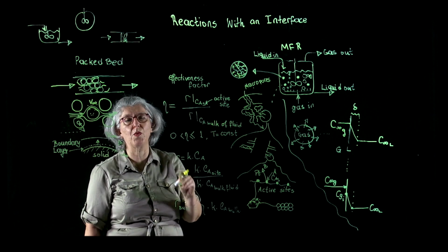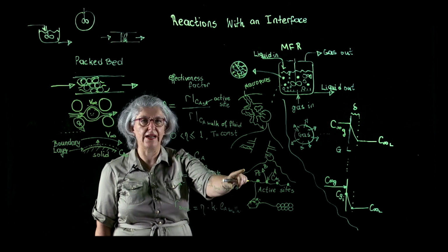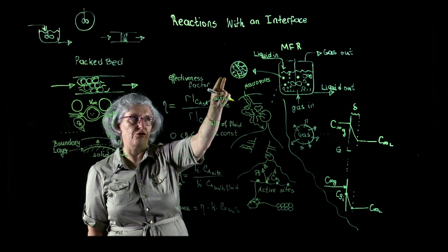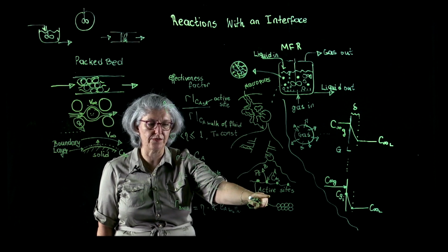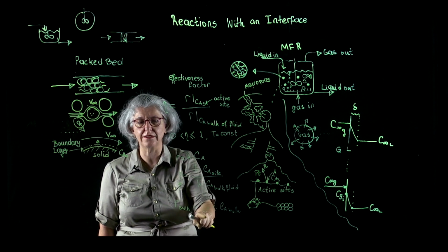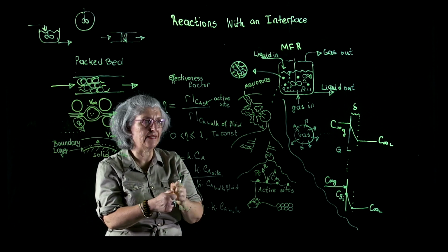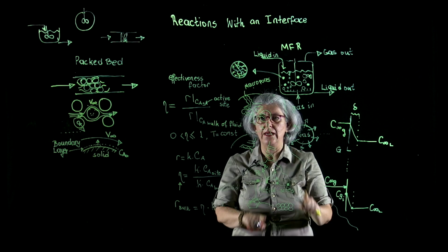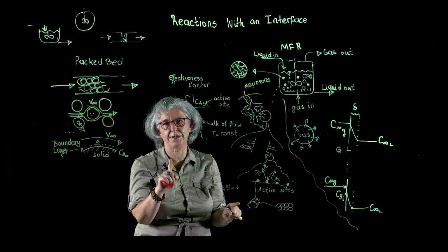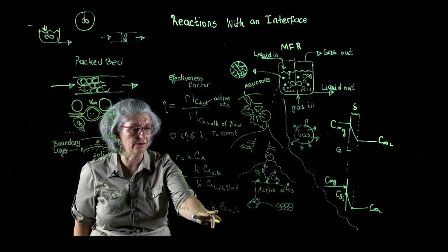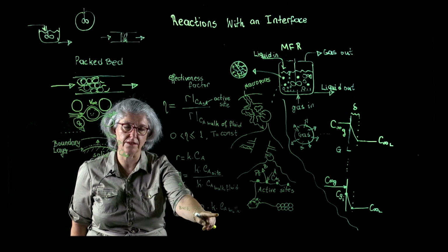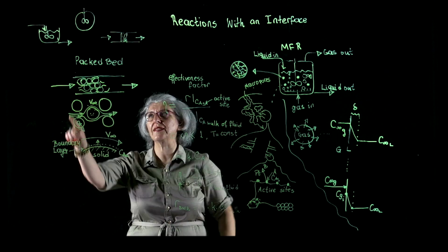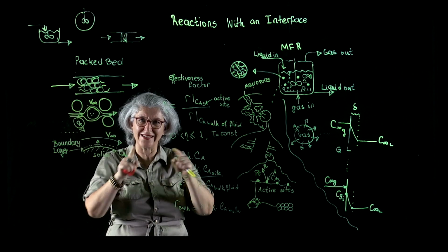We don't have to know the concentration at the active site. We don't have to know the happenings through the transport and on the surface. With a correction factor, we can simplify this complex physical process into a homogeneous, but this time pseudo-homogeneous, problem with a correction factor of the rate constant. Then we can just take this reactor and model it as a CSTR and size it.